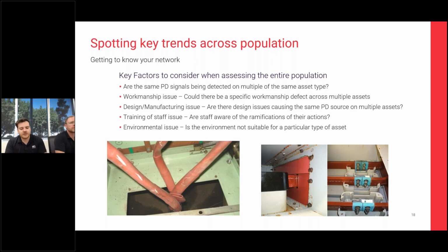What you have to be sure of is that whatever method of data analysis and trending you're using, it is capable of giving you the data in the analysis process for you to pick up on these types of trends. Specifically, with the UltraTEV Plus 2 and the method that Brad and I use, we always make sure to record things like your environmental readings, your temperature and humidity on site on the day of test.